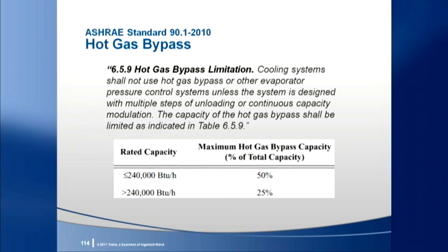During hot gas bypass operation, the compressor must be loaded at a higher level of compression than the resultant refrigeration effect. This is necessary so that hot gas bypass can trim the unneeded refrigeration effect and match the load. But the trim portion of the refrigeration effect is wasted energy and makes the system run at abnormal head and suction pressures. Abnormal pressures can also occur when the refrigerant heat recovery or hot gas reheat is used.